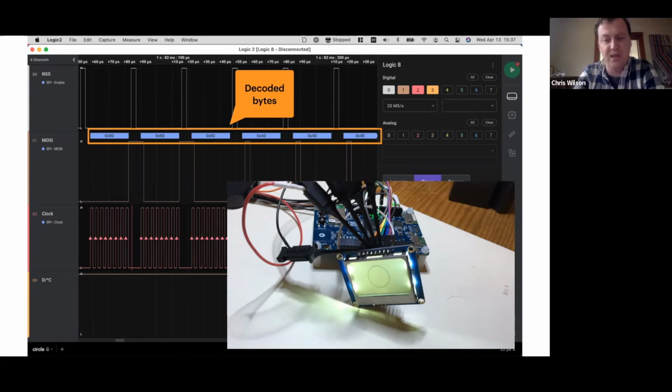I wanted to see if I was sending the correct commands, and this is writing individual pixels to the screen. And for a while, that was not working at all. And so I picked up this device to be able to snoop on that and see what was really going on. Yep, and so all these little connectors are the actual logic analyzer probes. You can kind of see it in the background there, but it's not a very good picture.